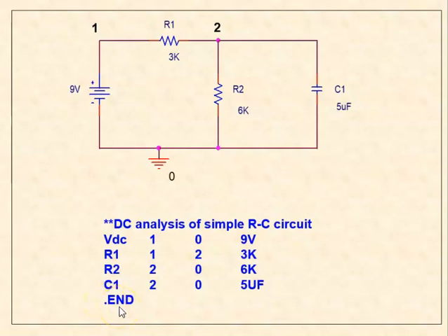All the PSpice commands start with a dot, so they are known as dot commands. The end of the program is denoted by the .end statement.